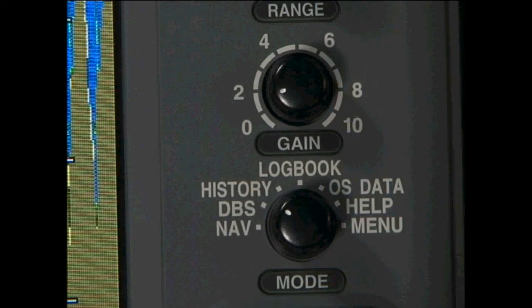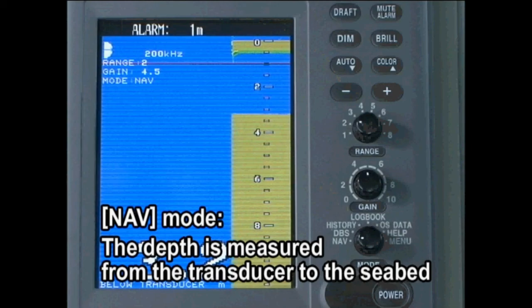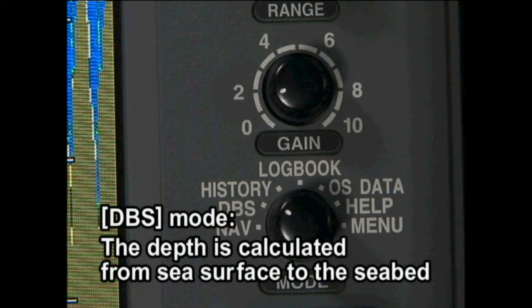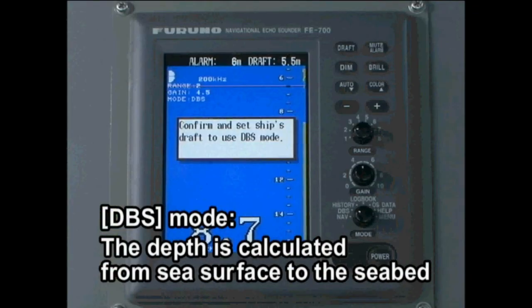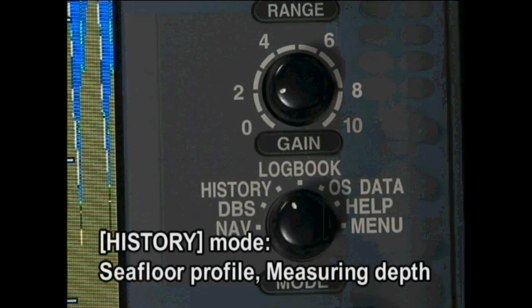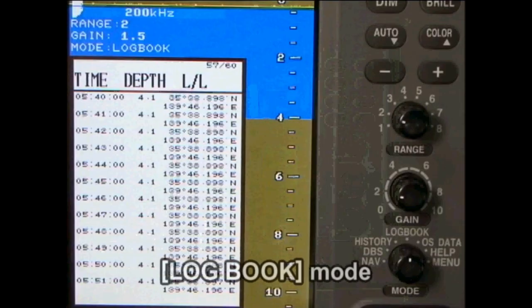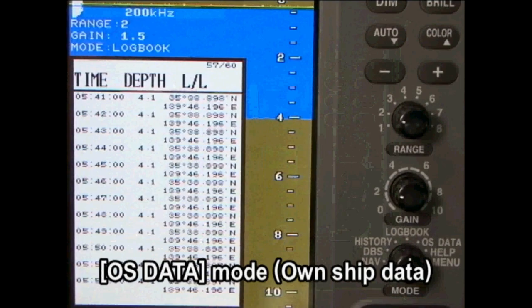There are 5 different echo sounder display modes. Nav, or navigation mode, is used to measure the depth from the transducer to the seabed. DBS, or depth mode, calculates the depth from sea surface to the seabed. History, or seabed history mode, displays the seabed profile and normal measured depth. The 2 other modes are logbook mode and OS data, or own ship data mode.